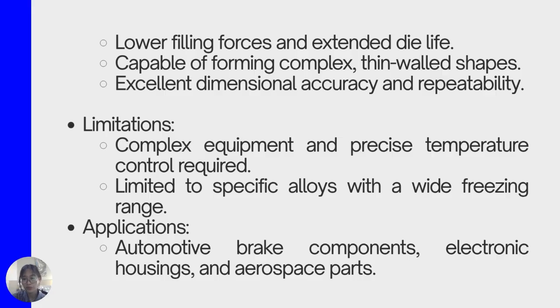It is capable of forming complex thin-walled shapes, with excellent dimensional accuracy and repeatability. Its limitations include that complex equipment and precise temperature control are required, and it is also limited to specific alloys with a wide freezing range. The applications for this are automotive, such as brake components, electric housing, and aerospace parts.